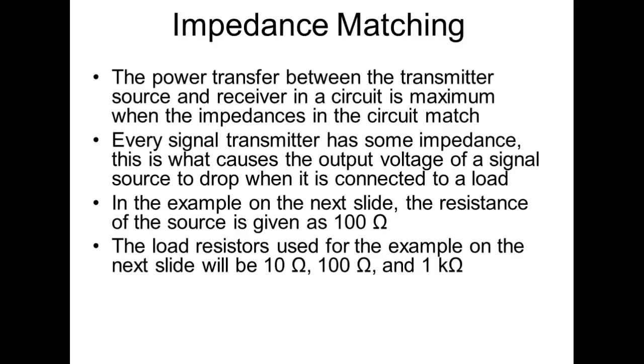They go bad, especially plugs that you use a lot. Plugs are not supposed to get hot, right? And receptacles and plugs, the cords are not supposed to just fall out of them either. So if you got a plug that stuff won't stay plugged into, what do you need to do? You need to change it. Go down to Lowe's and buy you one, less than $1. I usually buy them in the tin groups and keep them around the house. Change them out. They're not hard to change out, but I don't use those. I bend them and wrap it around.